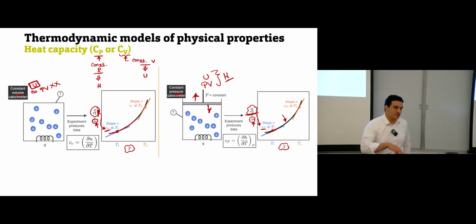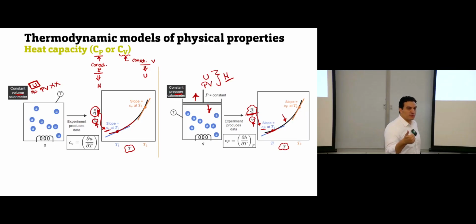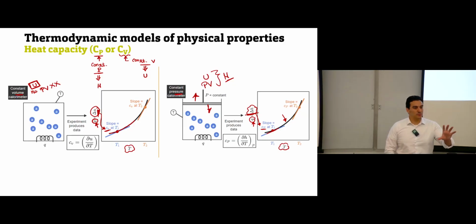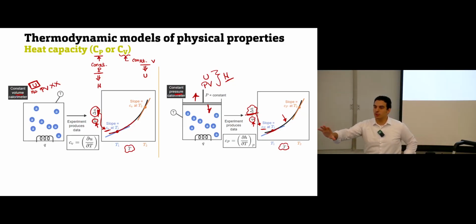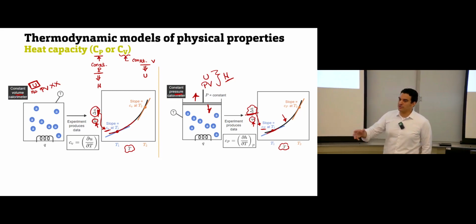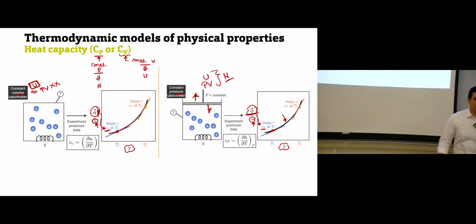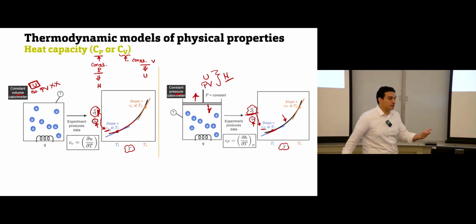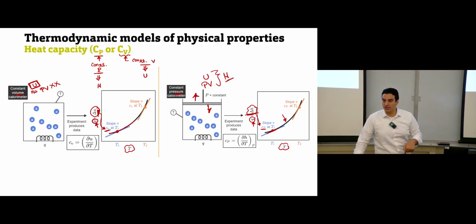So let's summarize all what we have. We start with defining enthalpy. Enthalpy is the summation of internal energy plus flow work, PV. We can find it from steam tables. If you have steam, go to the steam tables and find the value of enthalpy and the value of internal energy. So what if we don't have tables? What if we have a substance for which we don't have available data for enthalpy and internal energy? In this case, we need to calculate them.